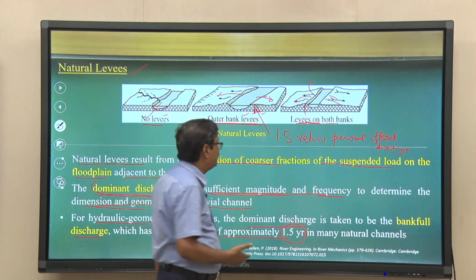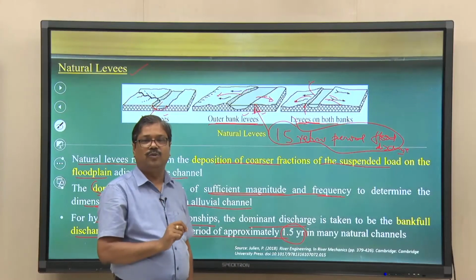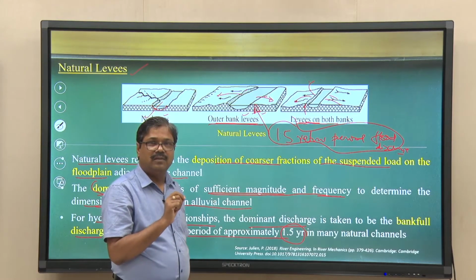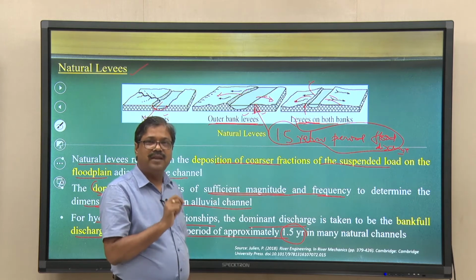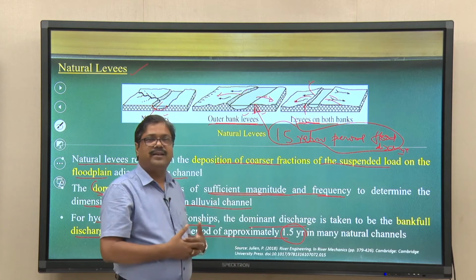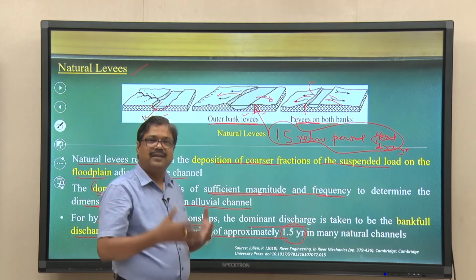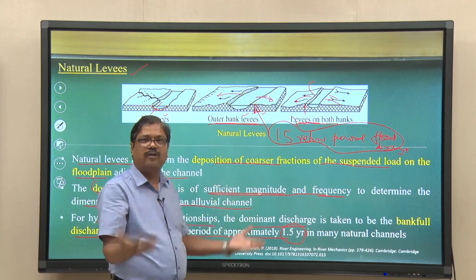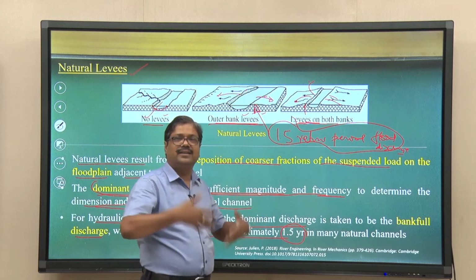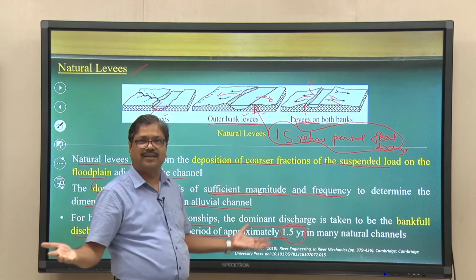Naturally, the bank full discharge is equal to the 1.5 year return period flow. That means a 2-year return period flood in a river is supposed to inundate the flood plain area. A 3 year, 5 year and 20 year flood will no doubt inundate a larger area.